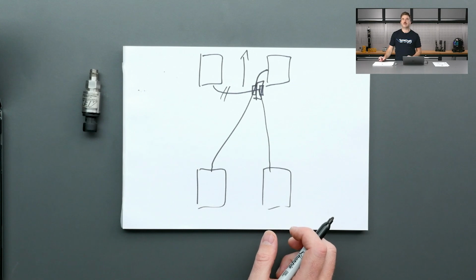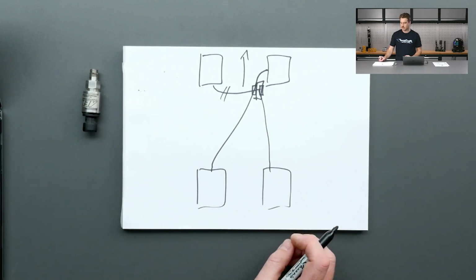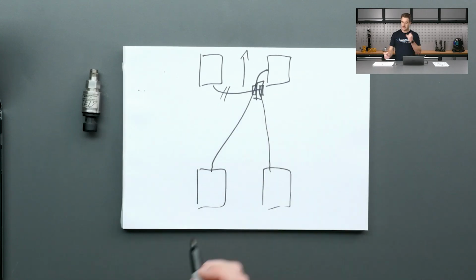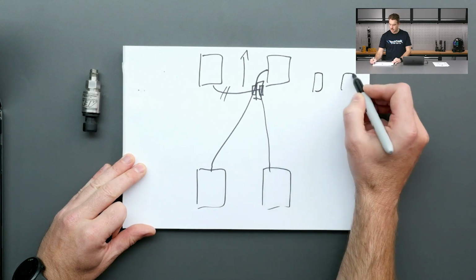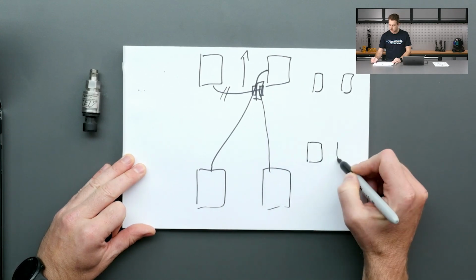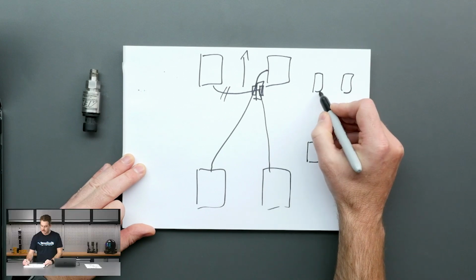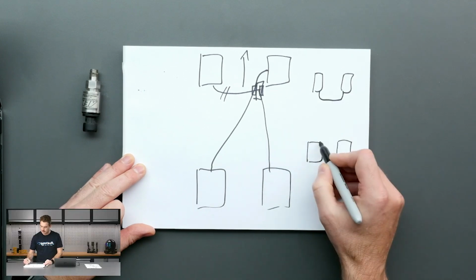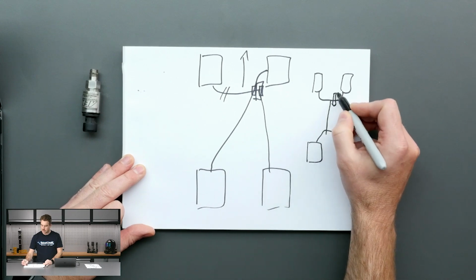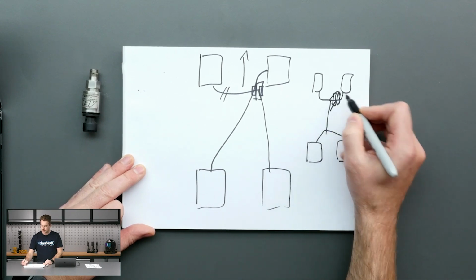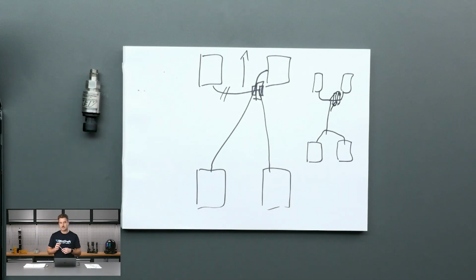Obviously, the braking on the front axle is by far the most dominant as far as making the car stop the quickest. So that's the idea behind why they're plumbing like that. In a motorsport context, we don't do it like that. We generally, I'll draw a separate one over here, have a separate front and a separate rear system like this, coming from two individual master cylinders. The idea here is that you want to be able to vary the pressure ratio between the front and the rear axle.